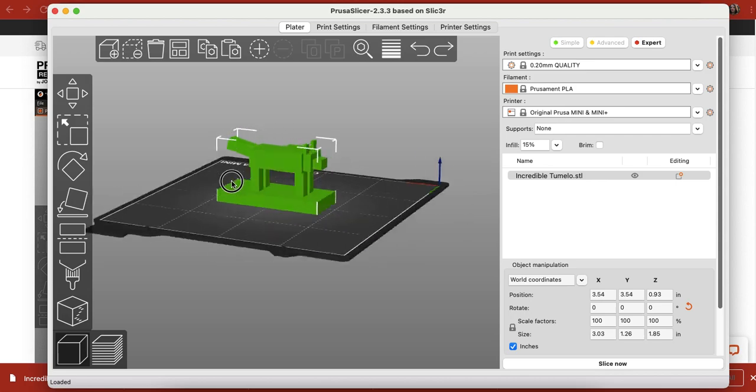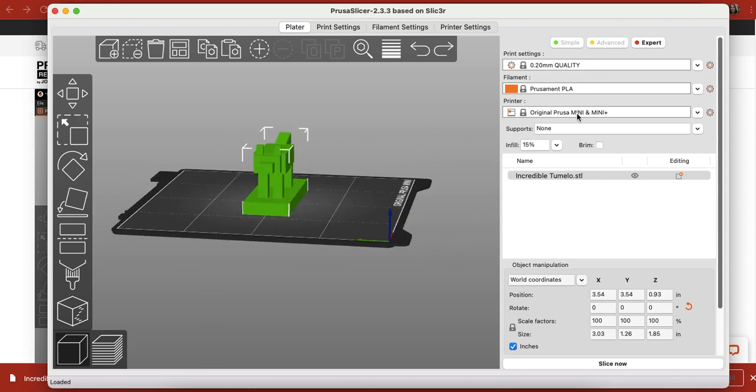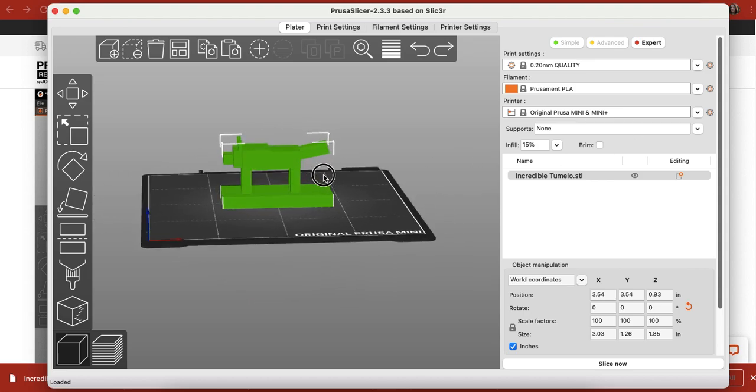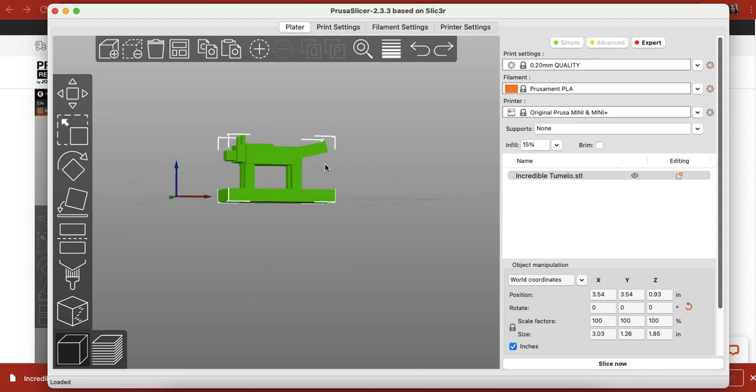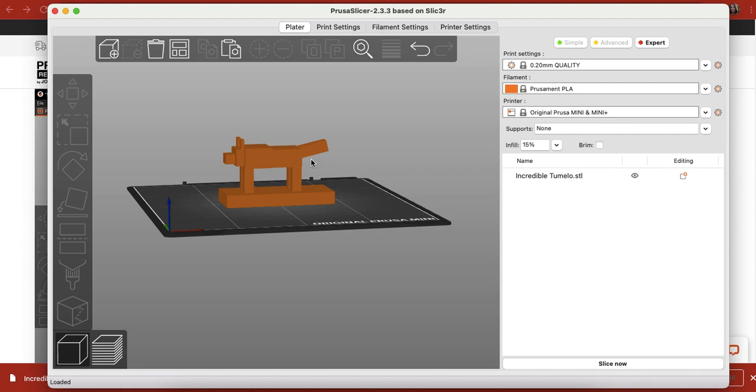Now, there are other options available as well. I have quality listed over here, the filament like I mentioned, and then we can also do something that's called supports. Support structures provide support when a print is printing layer by layer up. For instance, because it's going layer by layer, we can look at our wolf's tail. When it gets to this level, there might not be anything to support it, which means that our tail would fail by the time the printer got to this layer. So we want to make sure we have supports clicked.